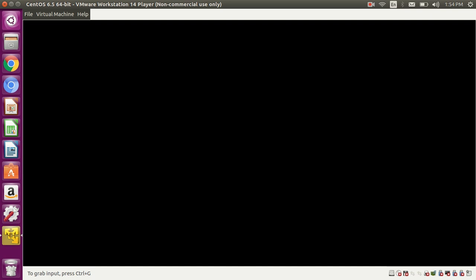More priority to hold means we can ignore the setup. There is a small setup variation, and with clock period adjustment we can fix that. But in the case of hold, one thing, be clear what my question is. The design is done, everything is done. You cannot fix it, you cannot change it. The silicon is out. There is a hold violation. Is it good? Can we go for silicon with the design? Why? Setup is met now.